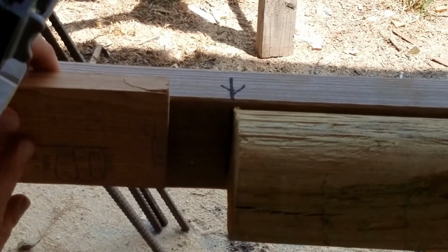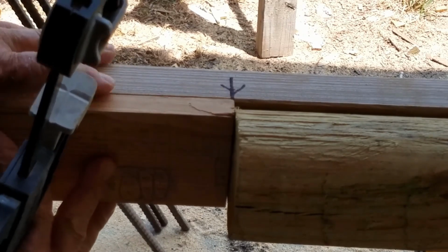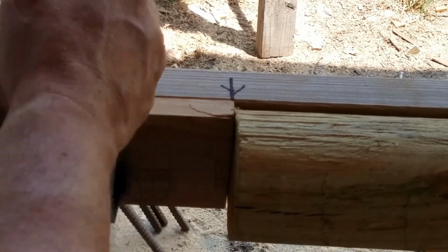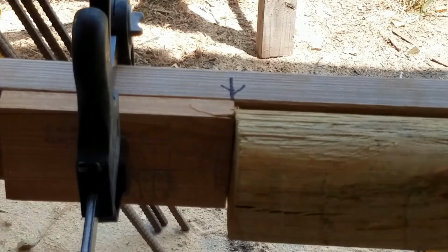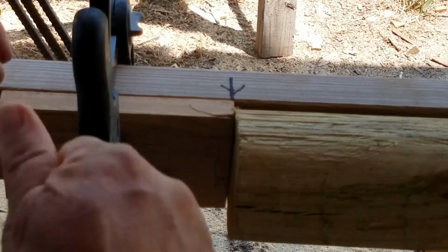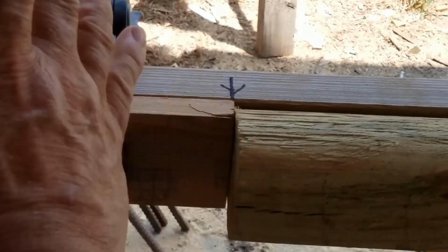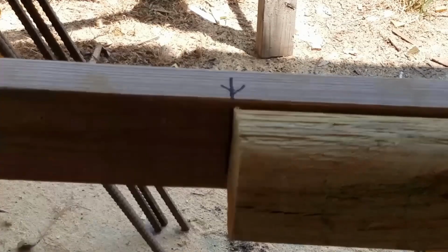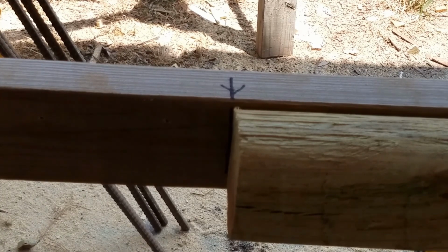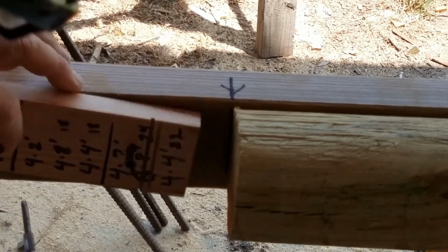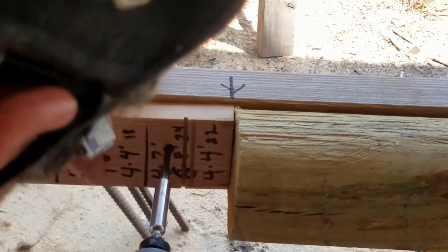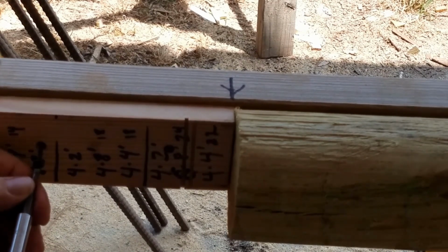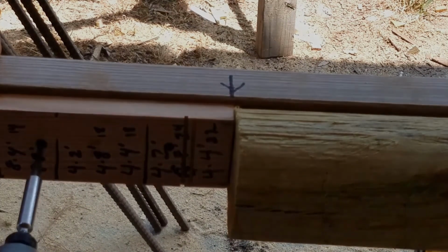You can also use a block and a clamp. Just slide the block right over to it. Clamp it. Now you just slide your wood over, bump your clamp, cut it. In this case, with some heavy material being used, I think I would prefer to screw a block up there. That way I don't have to worry about slipping. So you just take your block, slide it up to it. That's it.